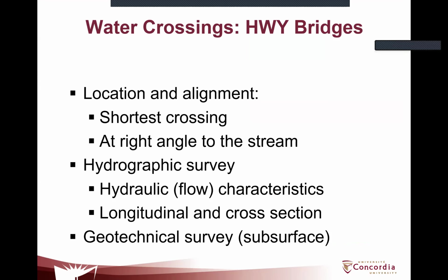So for the location of highway bridges, you need to try to plan for the shortest because otherwise you incur in a high cost at a right angle. You need to look at the hydrological characteristics as we commented. And you might need to look a bit on the geotechnicals as well to see if the soil has sufficient bearing capacity for the foundations of the bridge. You have to design those foundations.